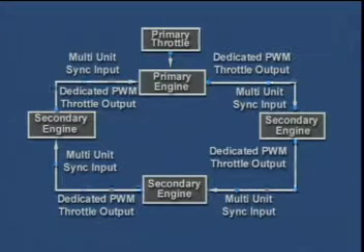The output signal from each engine is generated on the PWM out pin of the OEM harness. This output is then the input signal for the next engine on the VSS input pin of the OEM harness. The last secondary engine provides this as a feedback signal on the VSS input of the primary engine.